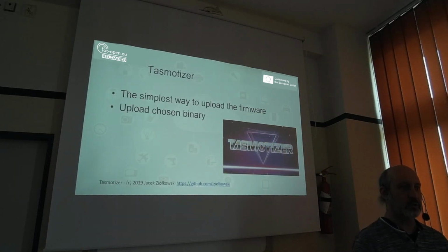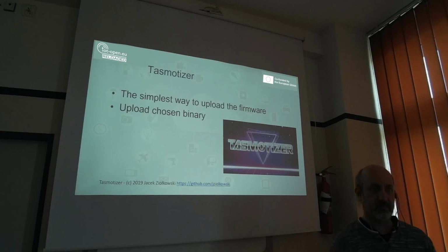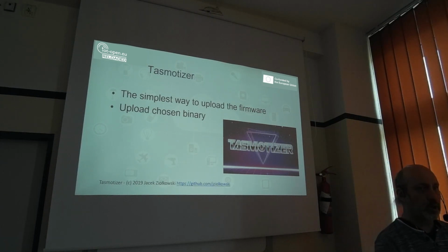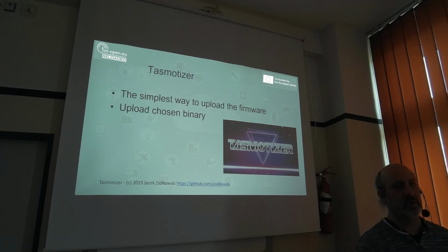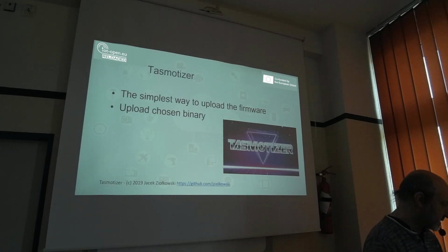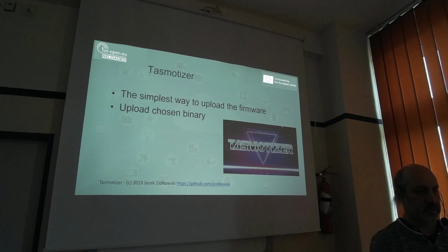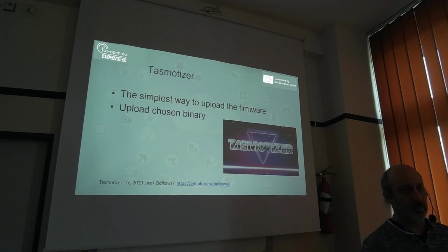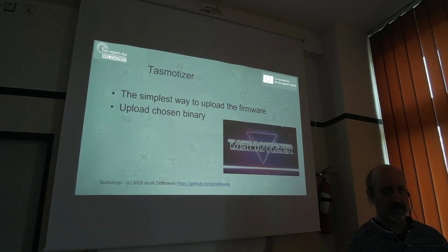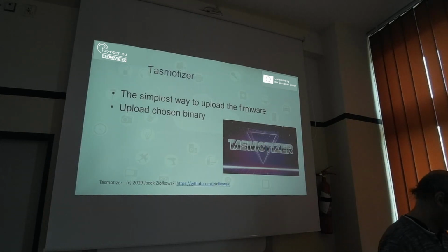The easiest way to upload the first version of Tasmota into your device, but not only Tasmota, any binary that you need to upload to your ESP8266, you can use the tool that is named Tasmotizer. Tasmotizer operates with a local USB port, like the Arduino framework. Yes, you can connect your computer using a USB port to an ESP-D1 device and Tasmotize, so upload the Tasmota firmware to this device.